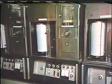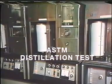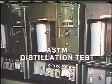Another test performed on the feed is the ASTM distillation test. This test identifies what types of hydrocarbons are in the feed by their respective boiling points. Hydrocarbons that boil above 400 degrees Fahrenheit should be kept out of the reformer because this heavy material will coke up the catalyst.